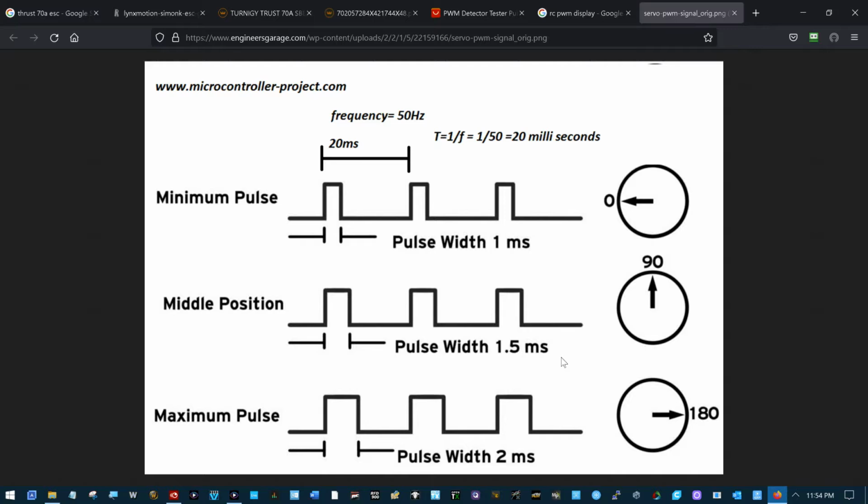It doesn't know it's low. It doesn't know the bottom number of that pulse width, the 500 we're talking about. Even if it knows the 2200, even if it thinks the 2200 is 2600, it probably will give you full throttle. But if it thinks the top is 1600, it's not going to give you full throttle. Just like if the bottom is 500, you turn it to 501, you're going to get a small RPM.